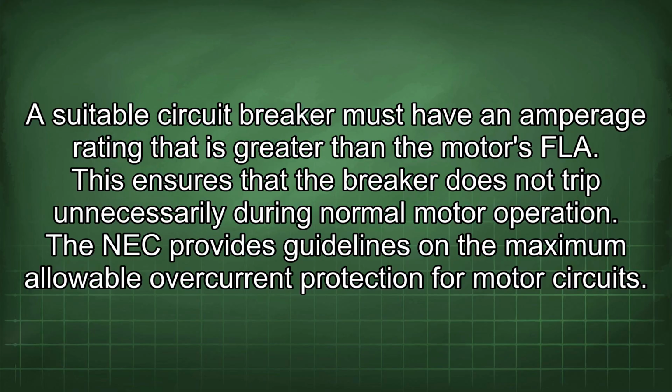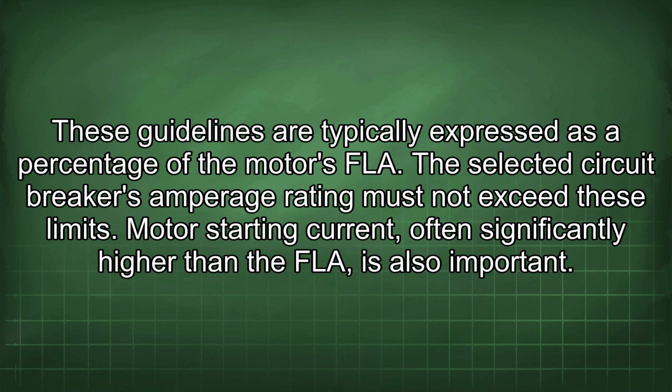The NEC provides guidelines on the maximum allowable overcurrent protection for motor circuits. These guidelines are typically expressed as a percentage of the motor's FLA. The selected circuit breaker's amperage rating must not exceed these limits.